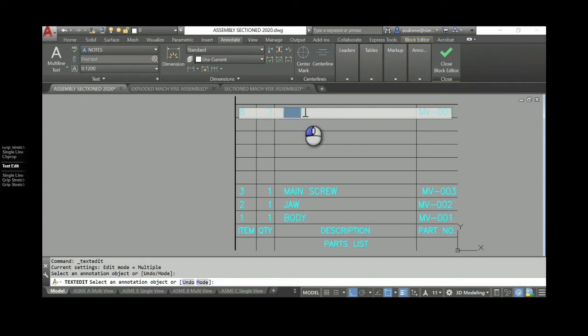When we do the flathead screw, there's not going to be a part number out here. Instead, you're going to give a full description: 0.250-20 UNC-2A FH MACH. Uh-oh, I need another line. That's why I did 9. Okay.